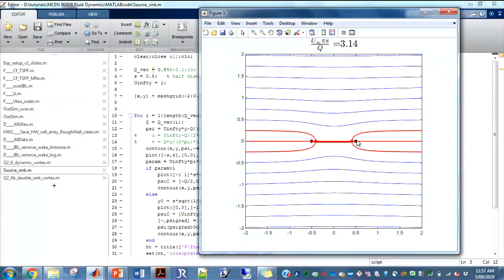So in that case, the flow here is going to the right, and just imagine you have a streamline coming out of the source, and in the beginning it wants to go left, but at some point the strength of the source is not strong enough to fight against the free stream, so it has to fold back at some point, and that kind of explains how you got this shape of the separatrix folding back, right? I hope this is convincing enough for you to accept this flow pattern.